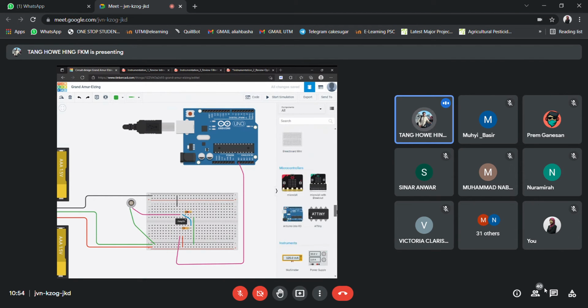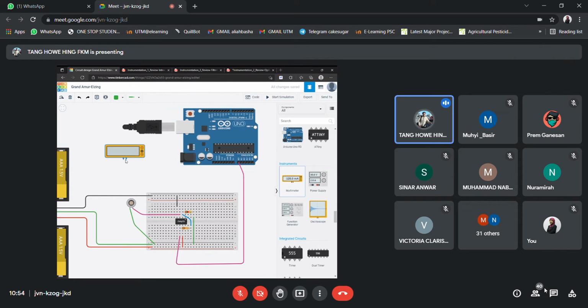This is one thing that I'm afraid of. All right, let me check. This thing goes to the ground. Oh, okay, sorry. I forgot one thing. You can see that this is a common ground, and this Arduino by itself also has another power supply. This is a power supply, and here there is another power supply. Therefore, if we want to connect them, we need to common ground the system. So this is the common ground.